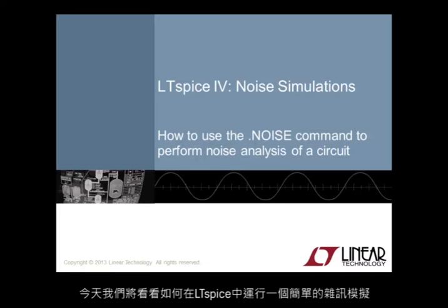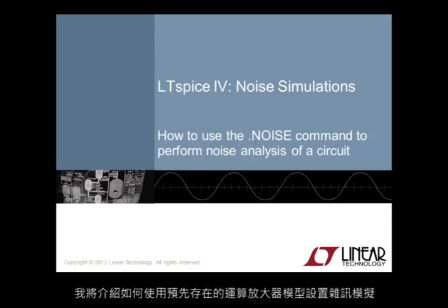Today we will look at running a simple noise simulation in LTspice. In particular, I will go over how to set up a noise simulation to view both input and output referred voltage noise using a pre-existing op-amp model. I'll also mention a couple of tricks to learn more about noise contributors.